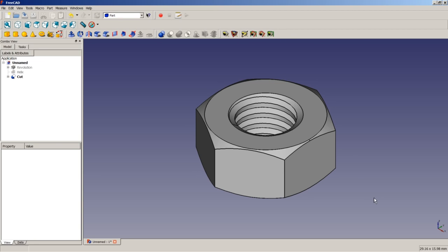I also encountered one time a situation with an earlier version of FreeCAD that OCC, so to say the geometric kernel, didn't seem to like the fact that the helix and the profile to be swept were lying on the same plane, in this case the XZ plane, as the revolved profile, which was responsible for the outer geometry.